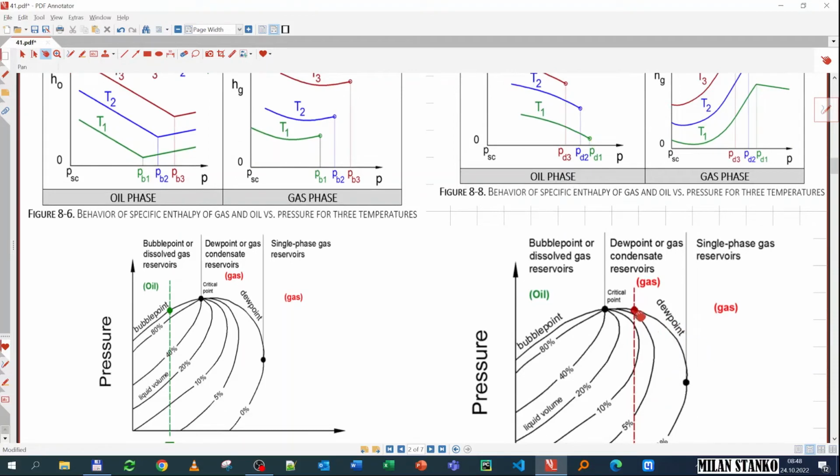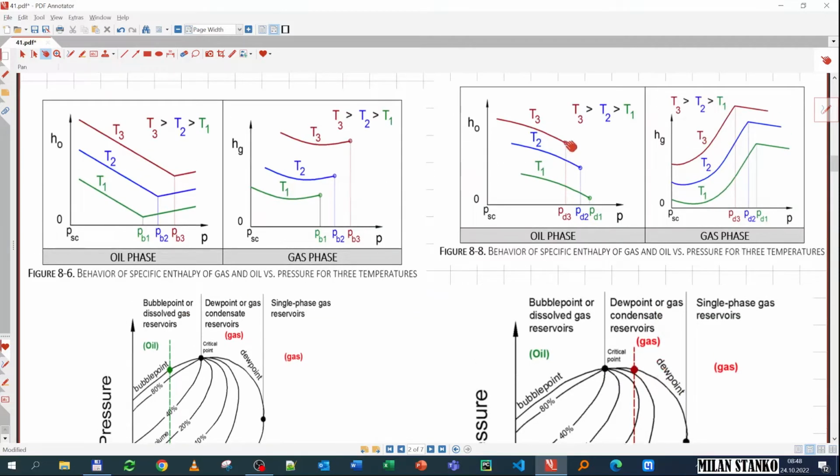In this case, if I increase the temperature, the dew point is going to be smaller and smaller, so the curve stops earlier at higher temperature. But that's how it is in this example. The gas has a bit of a trend going up, like an Rs type, a small Rs, and then it changes trend and goes down after the dew point. So that's how it looks.